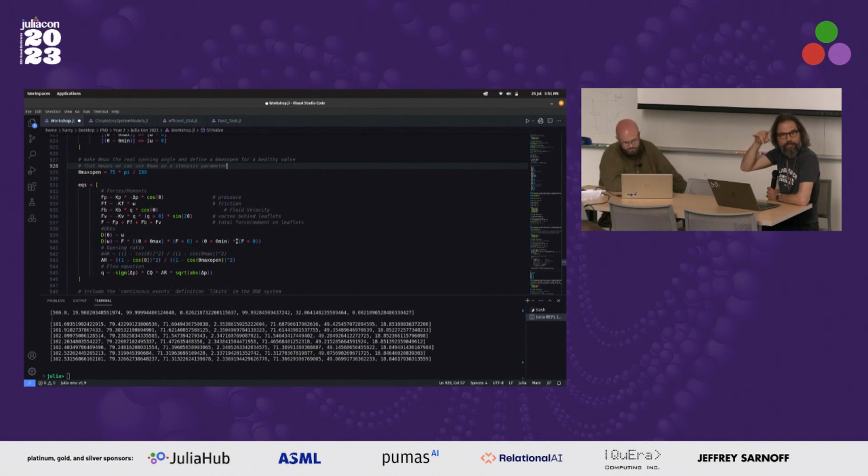That's what the Boolean operations are there for. And once it's at the closing angle, we want to set the acceleration to 0. So that Boolean is an addition of two Booleans. So one is always 0 and the other is 1, so that is all right.